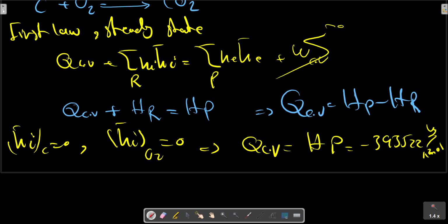The enthalpy of ideal gas carbon dioxide at 25 degrees centigrade and 0.1 megapascal pressure, with reference to this arbitrary base in which the enthalpy of the element is chosen to be 0, is called the enthalpy of formation.